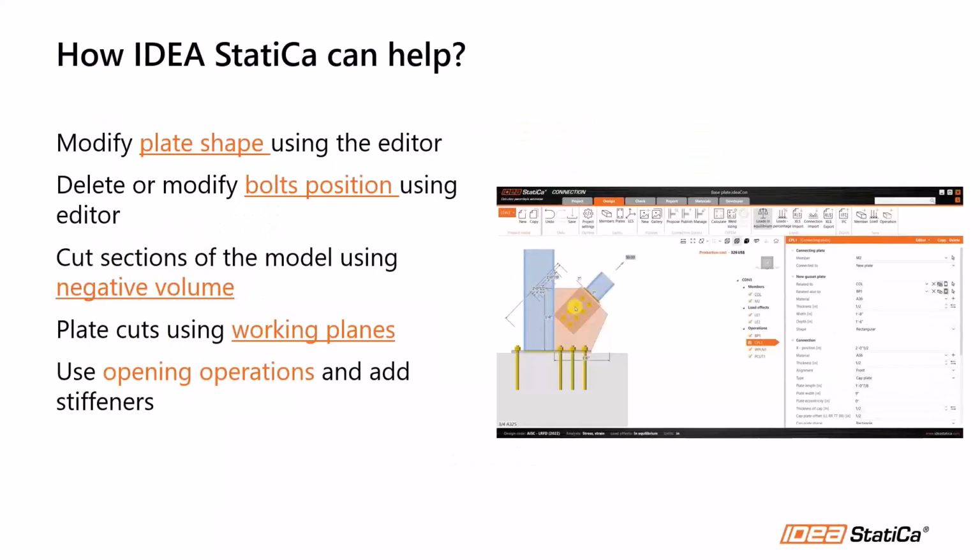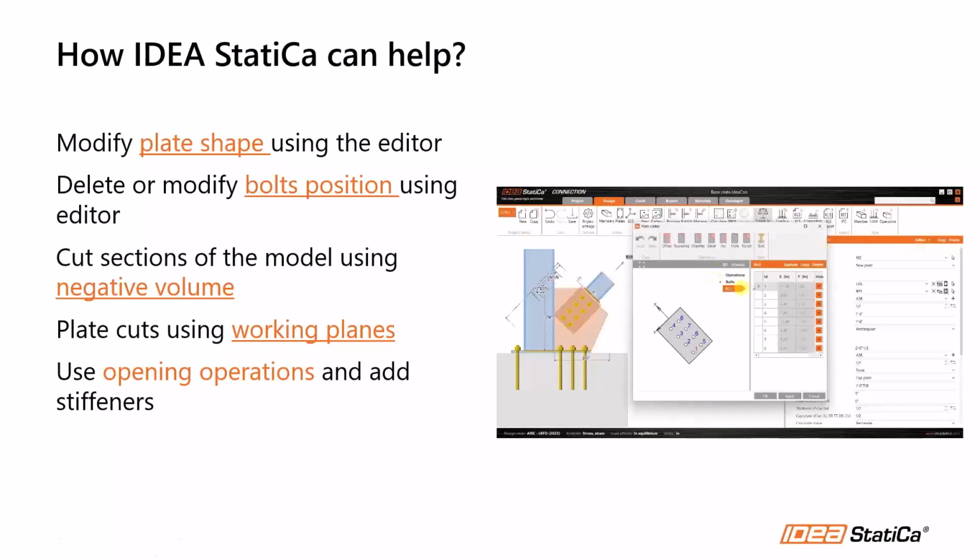So how does IDEA StatiCa help? Well, in IDEA StatiCa, you can use the editor for the different plates that you model in the main connection. The user easily deleted the bolts and reran the analysis to review the new stress distribution in the plate, right? And verified that the connection was okay with only 5 bolts.